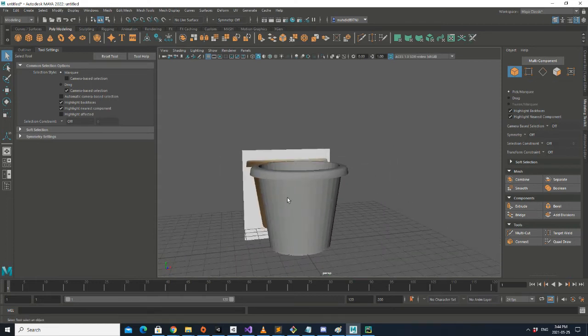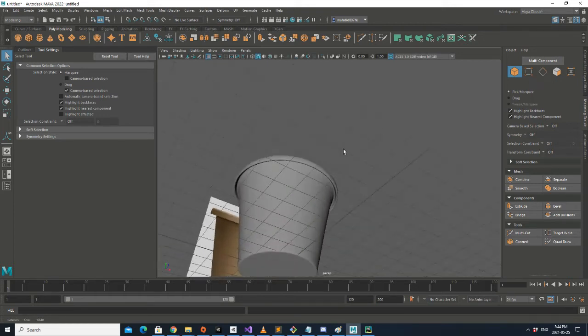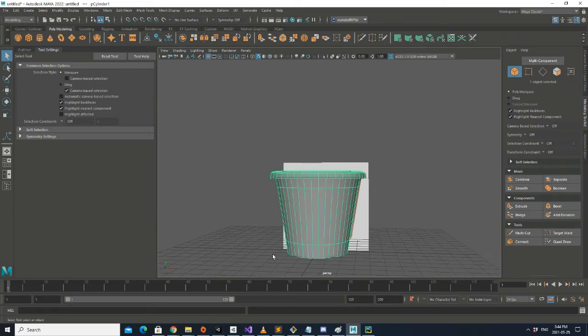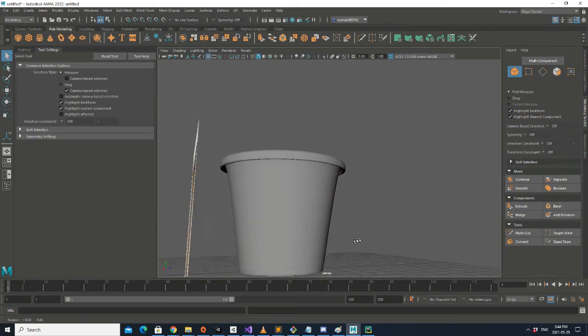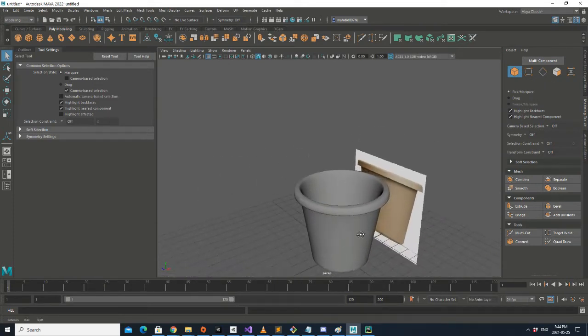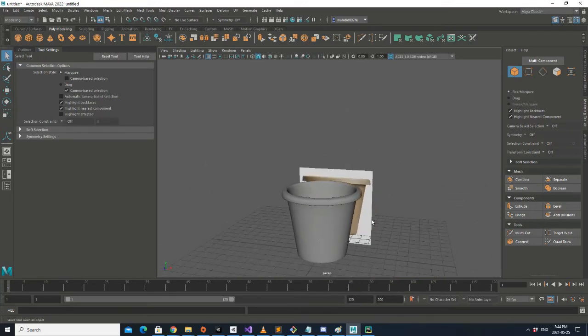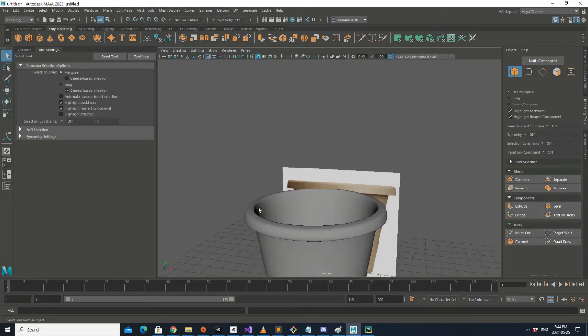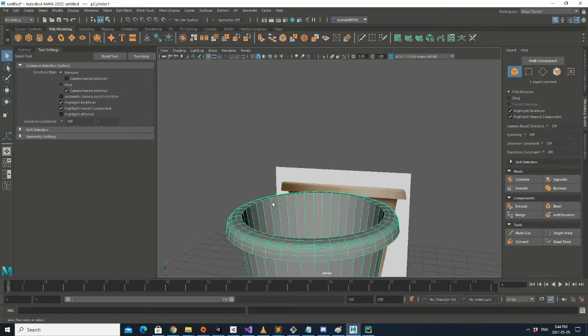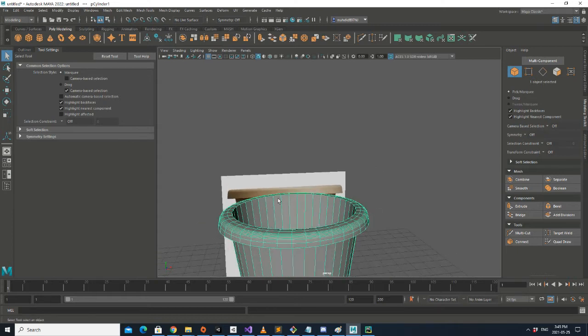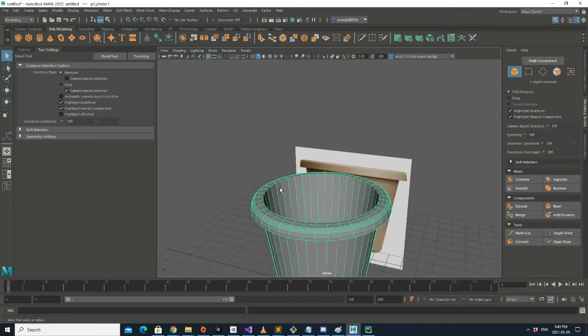If you make it smooth by selecting the object and clicking on 3, you see better fragments, a lot fewer than before. You see a smoother surface, but the problem is that it makes the sharp edges smoother too. You may not want to have that smooth effect there.